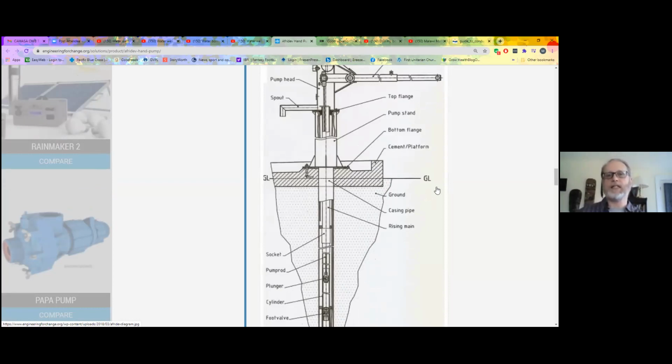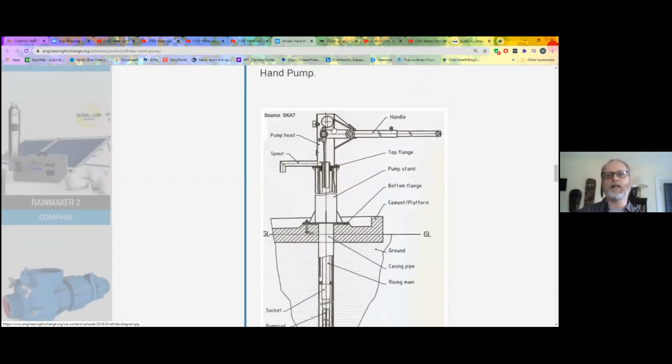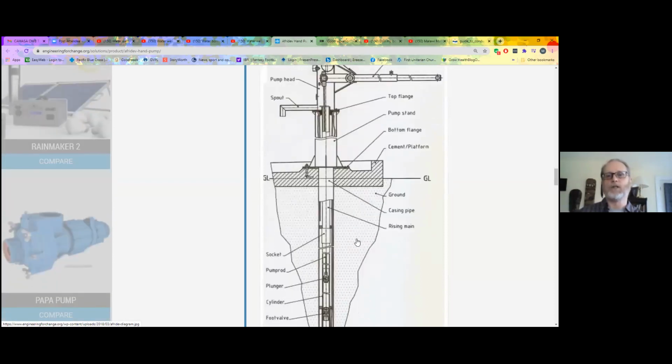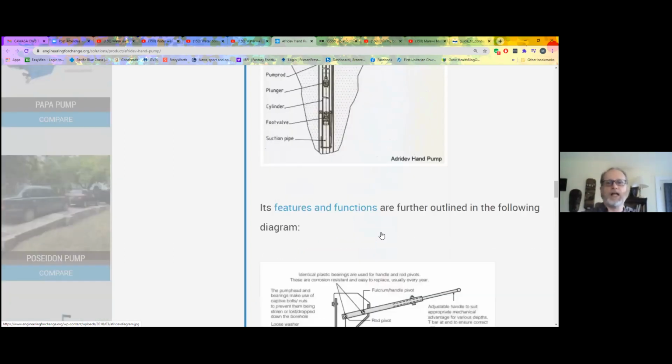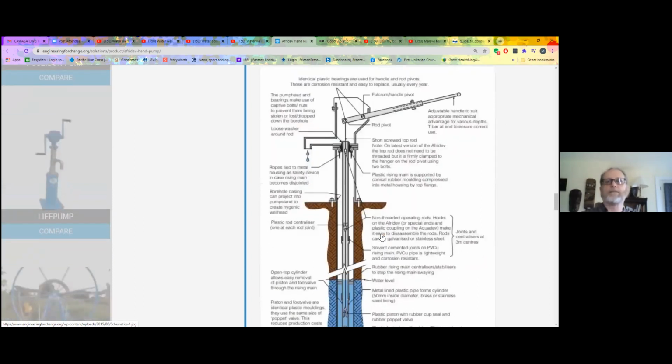So sanitary seal, this is all bolted up. The casing comes up in through the galvanized. That's set into the cement, flanged into the cement, and then basically a couple of bolts to connect to the actual rod, the pump rod that pulls the plunger up and down. So a very basic construction method, but that makes it durable and able to last in very difficult conditions.